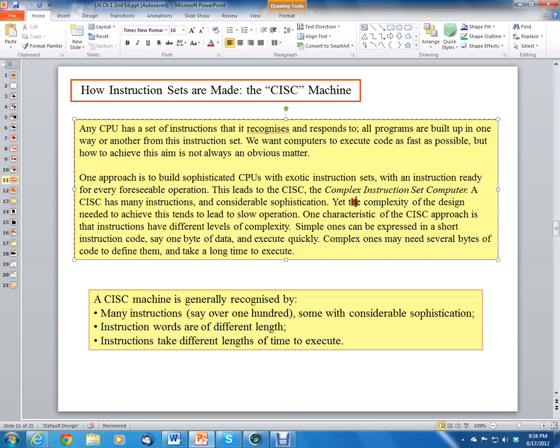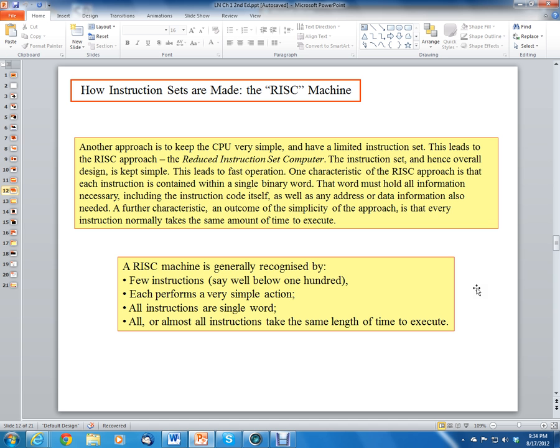So even though you have lots of instructions and they're very complex and they can do pretty much anything you want them to do instantly in one instruction, it causes you to have tons of instructions, and so the hardware, the silicon, the actual chip, has to be big and complicated and expensive. That's like your Pentium processor. But that's not what we're going to be talking about in this class. We're going to be talking about mostly RISC architectures. That's what's used for most embedded systems.